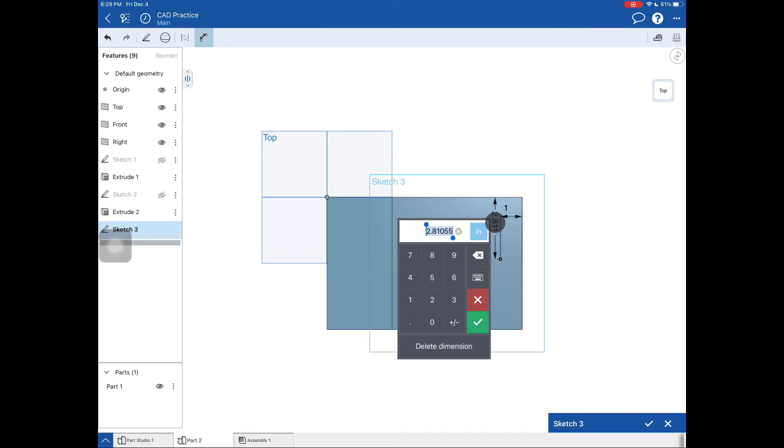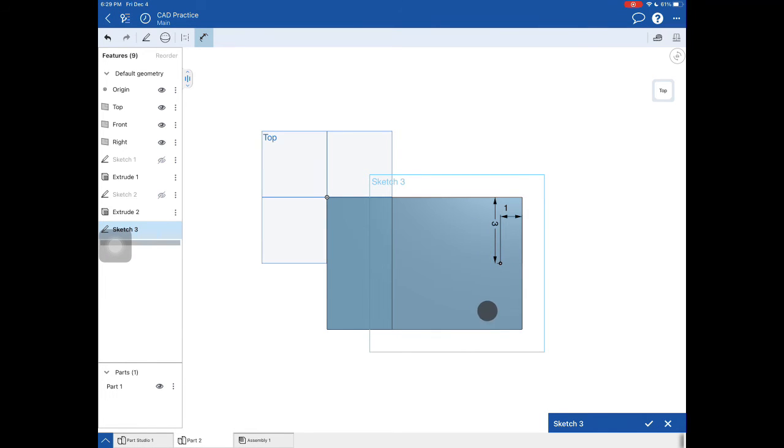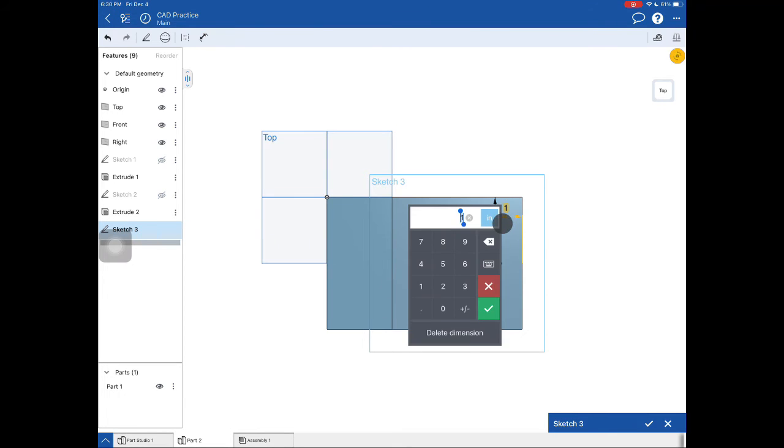So I'm centering my hole or drill point. If you took woodworking or any other classes that required this, you're going to identify where the center point or the center location is for your hole. So that would be a point that you would center punch prior to drilling.